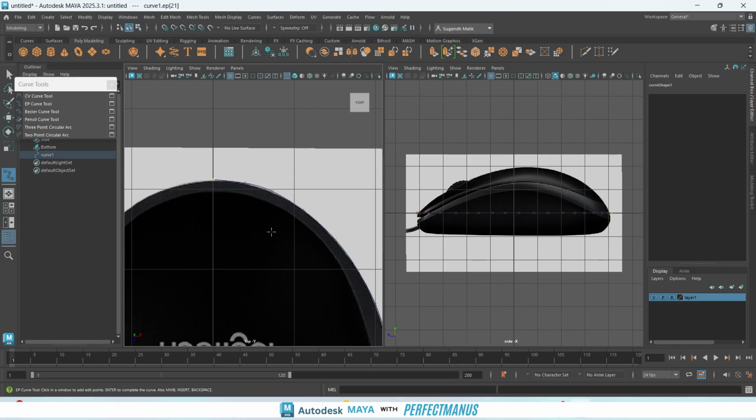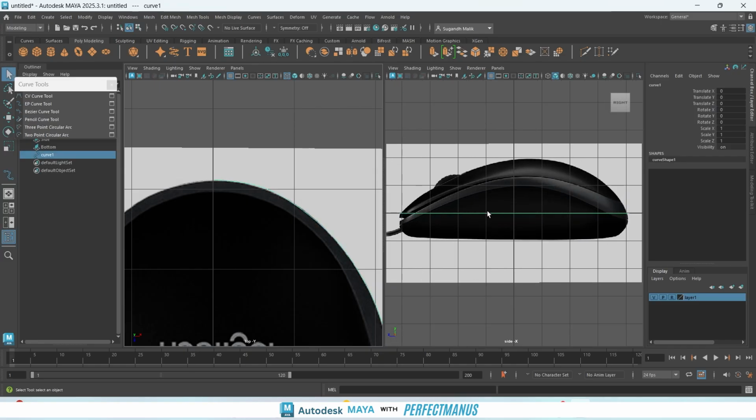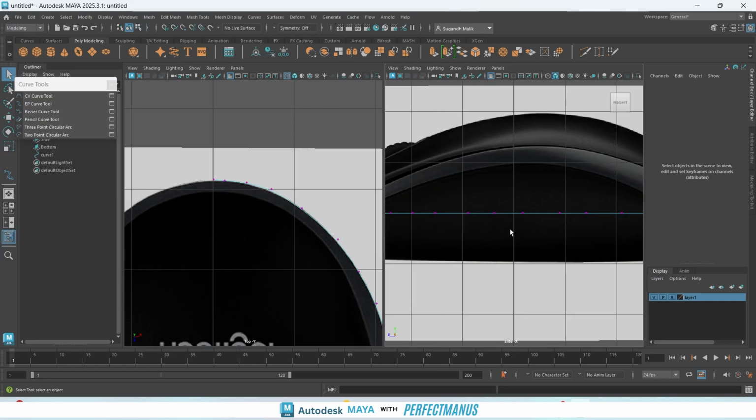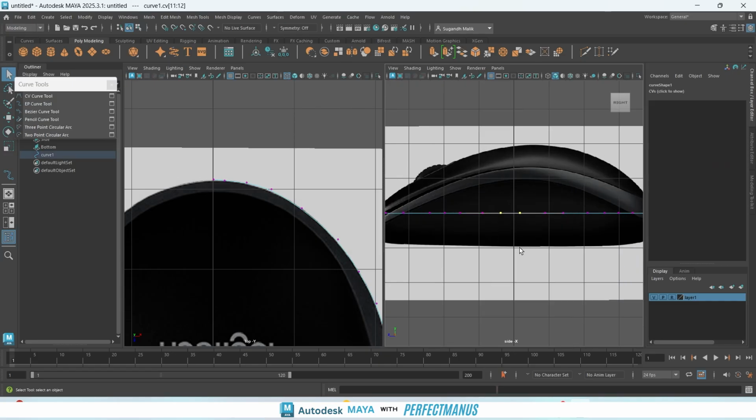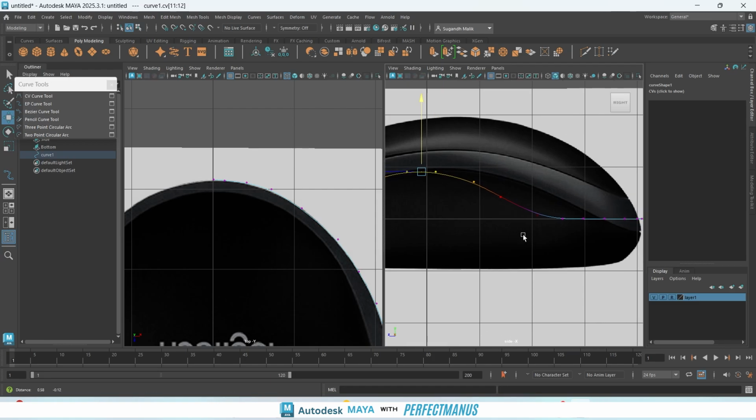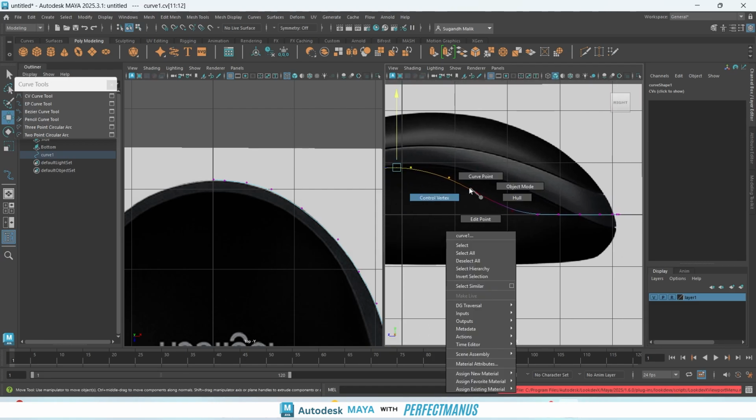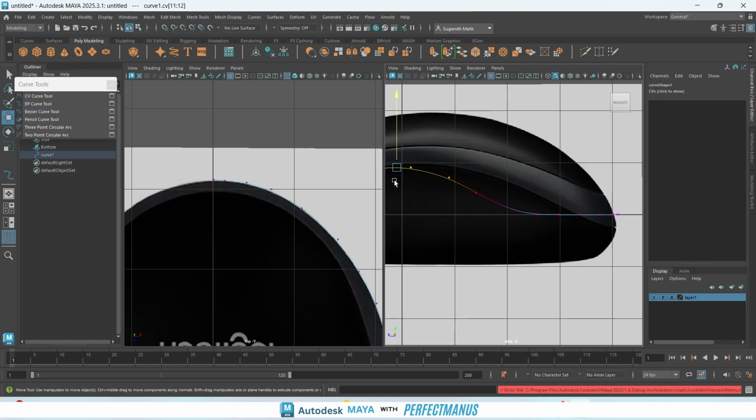So it's done till here. You press Q, okay. Now by pressing on control vertices, you start moving them up, okay. So by pressing B, it will enable your soft selection. By holding B and your middle click and dragging it will increase the area of effect. Now we will be moving them up till it's there. So as it's a curve, we don't move them too much because while you move another point beside it, it will also shift that one, okay. So you can see even if I disable the soft selection, when I move it up, it will also affect this area.